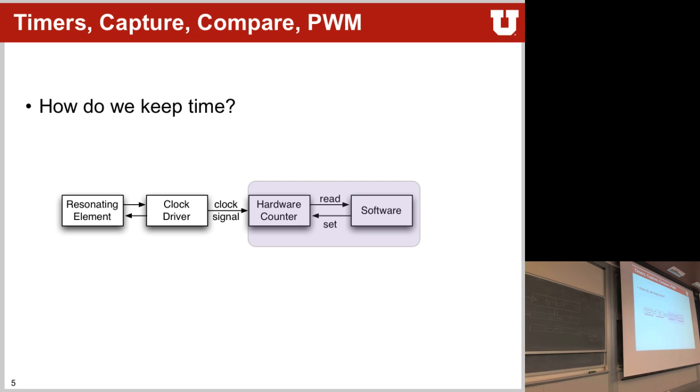Yes? Right? PWMs are defined by a period and then a percentage in between. So we have a signal that's low and comes high for a certain amount of time and then keeps going. So we have a period here, P, and you have a width. Let's call it W in our case. So you basically need 2 compares, one of them will be the period of your signal, the other one will be the duty cycle of your PWM signal.